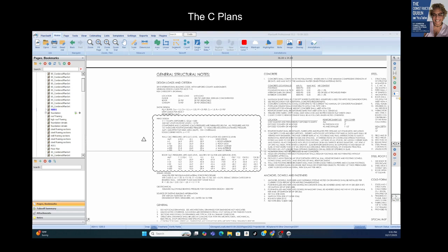For the lateral loads, we have the shear walls, right? We frame an existing wall in certain positions with extra plywood and tighten it up with a lot of nails and additional framing over the existing framing. Those are the shear walls and braced walls. Those take care of the lateral loads, and that's our lateral load path. So shear walls, diaphragms, and anchorage and hold downs. We all know what those are if you look at a set of plans.